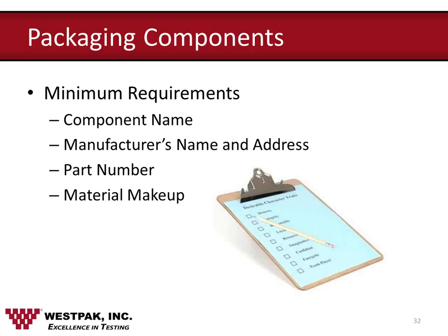This is very important, especially for material makeup. For instance, you cushion your bottle with 1/2 inch of cushioning material, something happens in the field, and then they measure this cushioning material and instead of 1/2 inch, they measure 1/4 inch. Now there's a discrepancy because the thickness is different than what was specified. Did this cause the failure? If it did, there are going to be fines associated with it, and you have a chemical spill to clean up, and it's just a mess. So documentation is required for traceability.